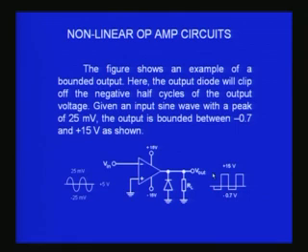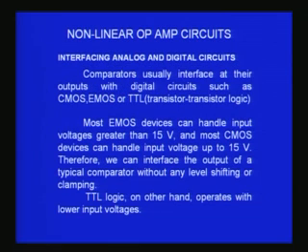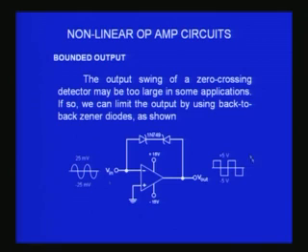So, this is one way. It will also be still better if I can control the two voltages on both sides, plus 5 to minus 5 or plus 3 to minus 3 and things like that. For that, we can think of another application, and this is the circuit which I show now, where I have used in the feedback two diodes, two Zener diodes to be precise. For example, I have used 1N749, which has a breakdown voltage of about 4.3 volts, and they are connected in opposition. One is connected in this direction, the other in the opposite direction.